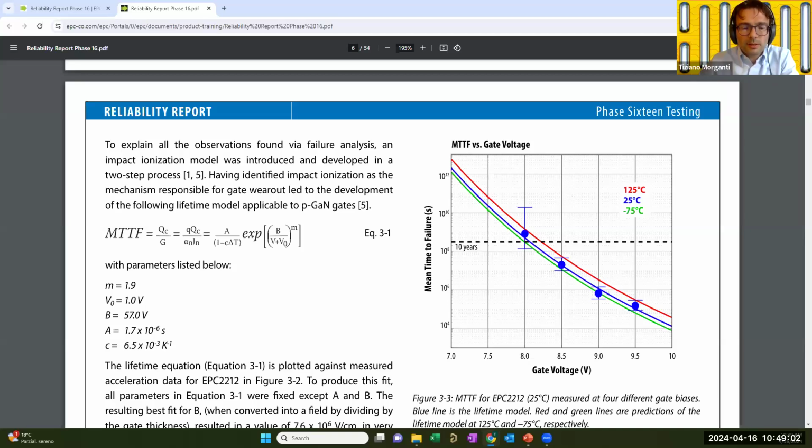It's Schottky gate structure, and the advantage is the drive is dependent on the voltage, so you have just to charge the capacitances on the gate. So compared to GIT, you don't have to provide any bias current.